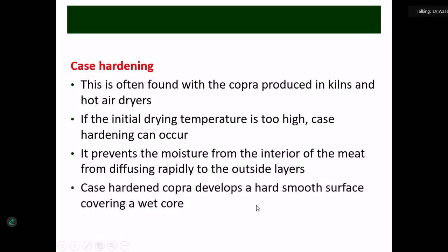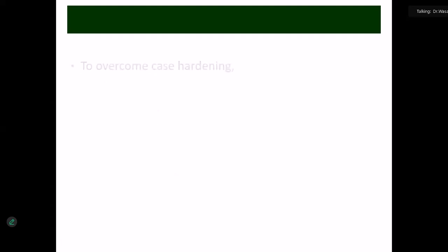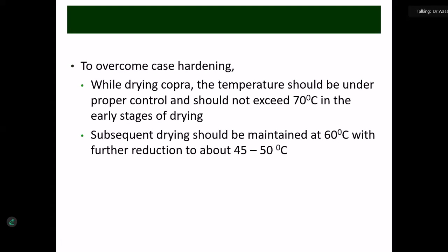Case hardened copra develops a hard, smooth covering over a wet core. The inner side is wet. To overcome case hardening, what should we do? You should not exceed an initial temperature of 70 Celsius. Maximum temperature should be 70.